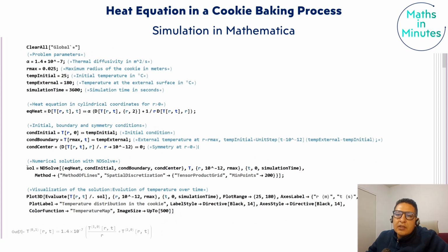After that, we will use the NDSolve function already implemented in Mathematica. And here the way to write it is that we have to write the equation and all the other conditions that we already have. As you can see here, I use just one equal sign because this is just to assign this element to this variable, and here I use two because this is a mathematical equality, right? I think it's clear enough.